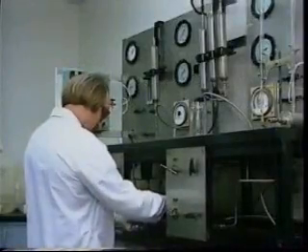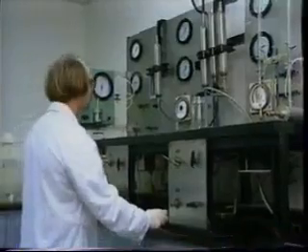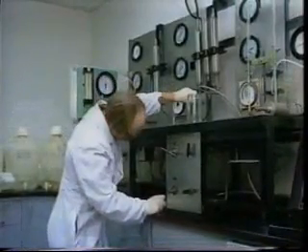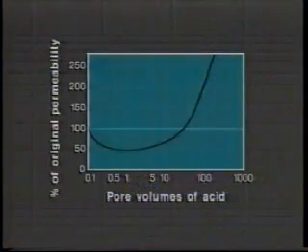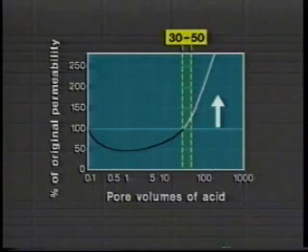Unless we are able to perform acid tests on core samples, the volume of HCl-HF acid is more complicated to determine. We generally assume that a matrix acid job using HF acid will penetrate only 3 to 6 inches before it is spent. Core flow tests have consistently shown that core permeability is reduced until 30 to 50 pore volumes of acid have been produced through the core.